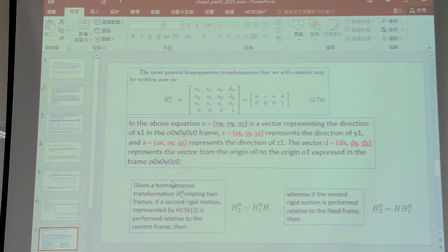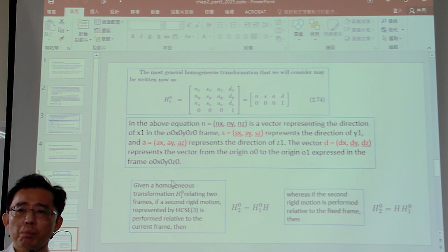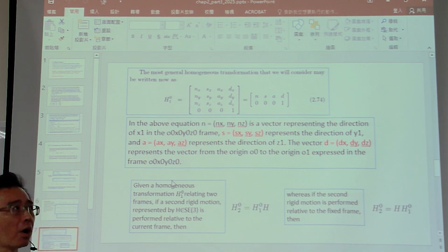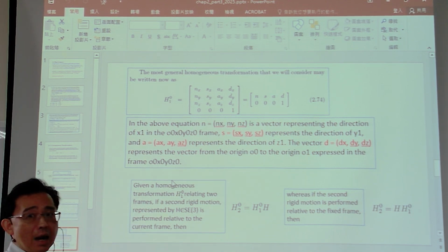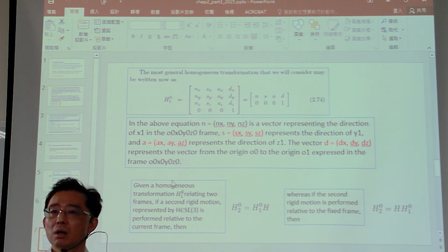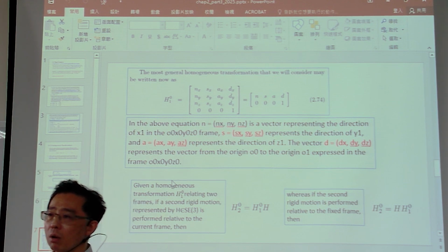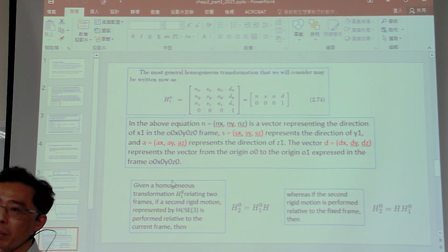So when you move to somewhere, for example, if you have an end effector on a robot and you move to somewhere, this is somewhere we have a position. So we have dx, dy, dz, they will be fine. But what is the orientation? What does the orientation mean? It means you need to pull up your finger. If the finger points to somewhere, they will have a different NSA matrix. So you have a different NSA value for the pose. Then you need to do the inverse kinematics to compute what is the rotation angle on our robot.